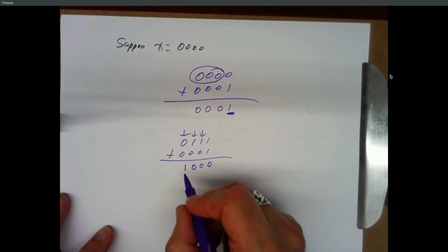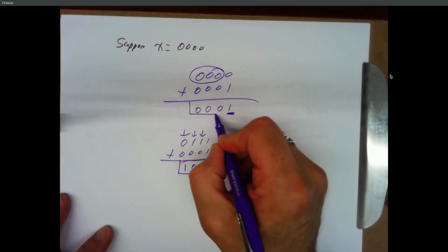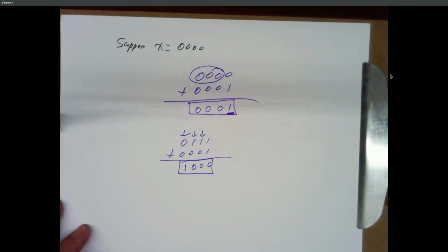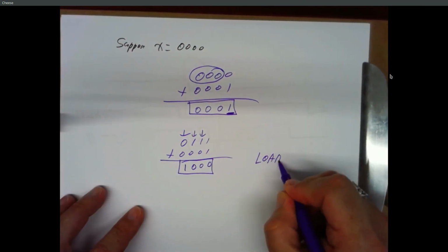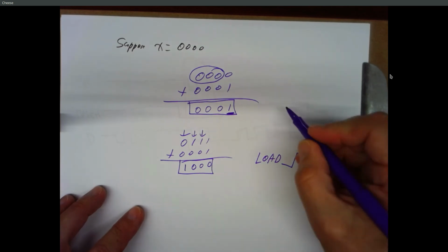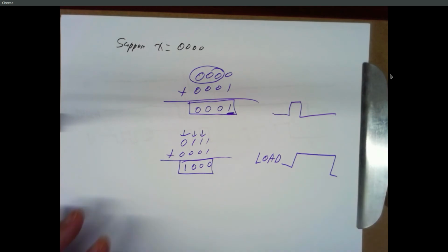But it takes roughly 4 times as long to get this answer as it did to get that answer. So in this case, that load line would need to stay high for 4 times as long as you needed in that first case. And this is a nightmare to try to deal with. Now there's people who deal with this. I like dealing with this myself. But it's kind of a nightmare because the timing is so touchy. Leave the load line high for too long and you end up adding multiple things. Leave the load line high for too little and you might not have enough time for the adder to give you a correct answer. And you end up with gibberish.